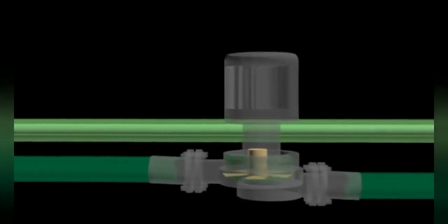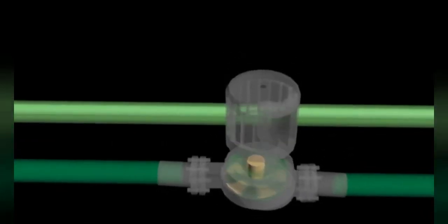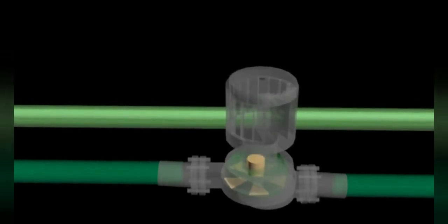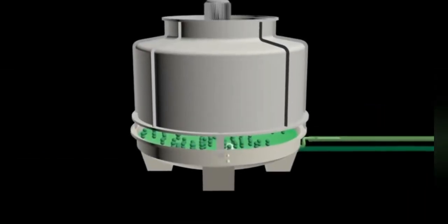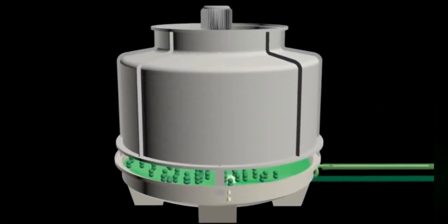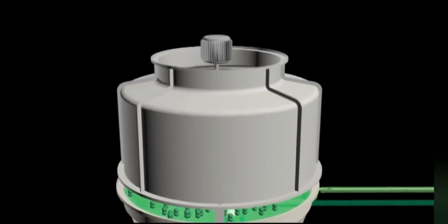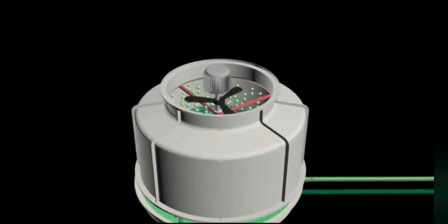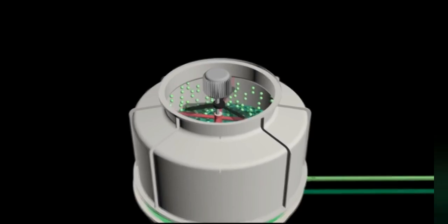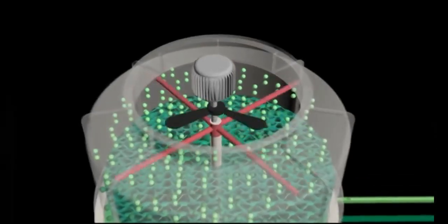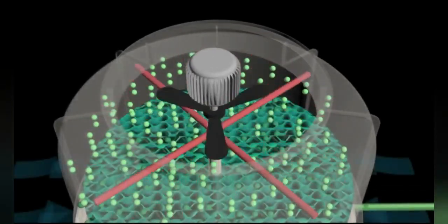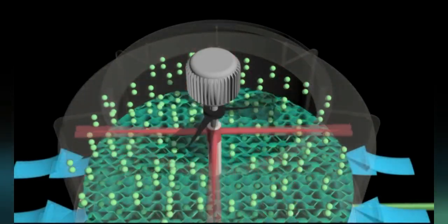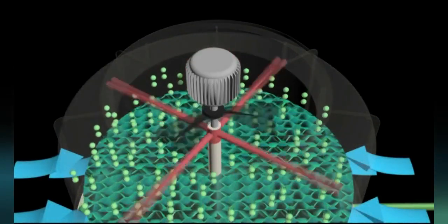From the condenser in the chiller, condenser water flows to the cooling tower with the help of a centrifugal pump. This water is called condenser water return. This condenser water will pass through the rotating sprinkler blades on the cooling tower. These rotating blades use pressure generated by the condenser water itself. Water will gush down through the fins to reduce the speed of the water going down.